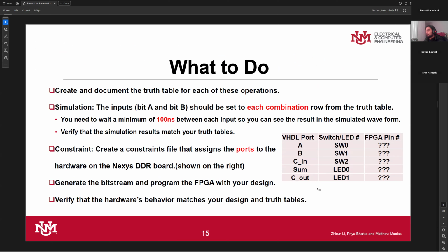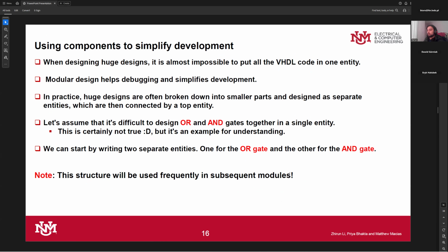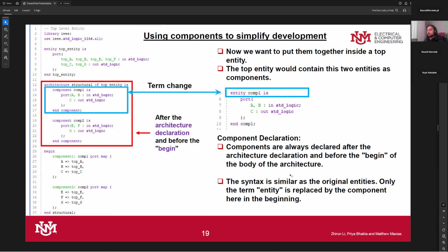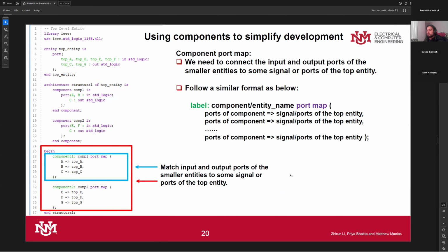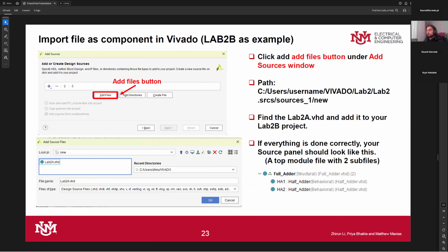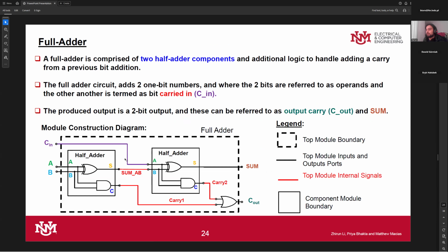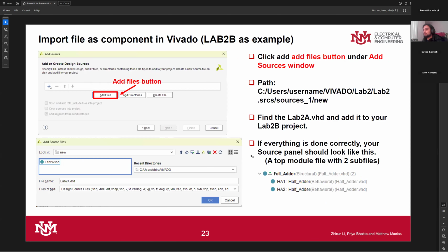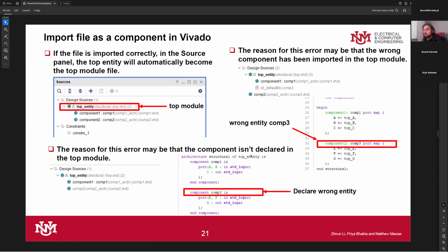Pretty much the same as before. But the last part that we added, where we also include the C in, right here or right here, included an extra bit, so we'll get a one in the carry bit and one in the sum bit as well. If that doesn't make sense, please be sure to ask some questions.